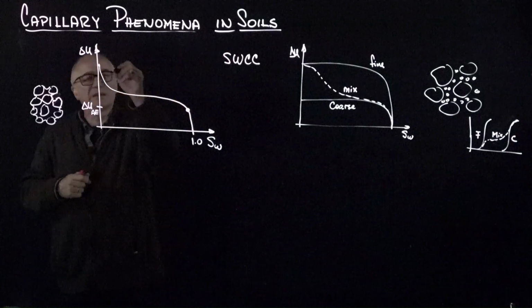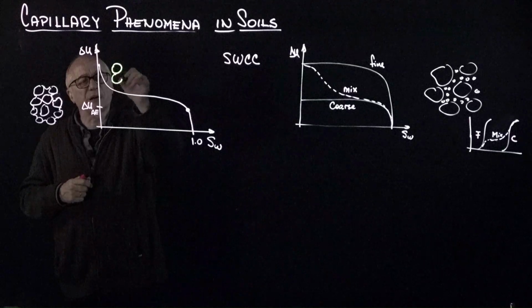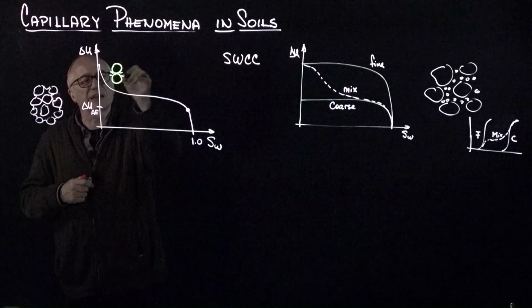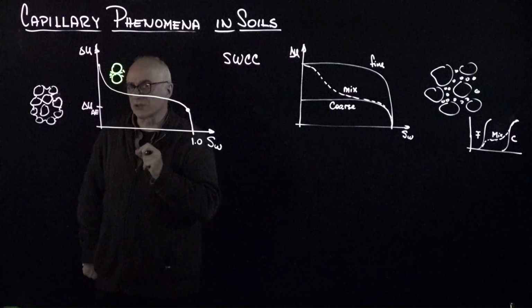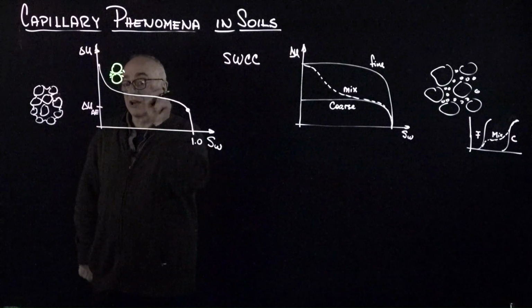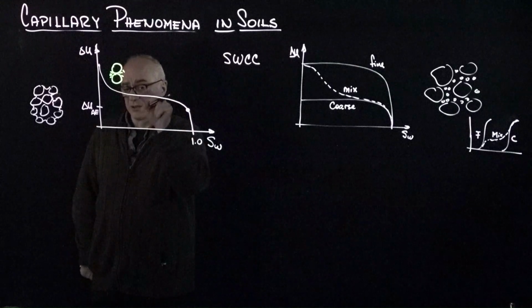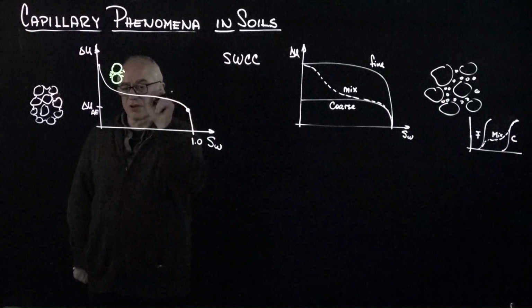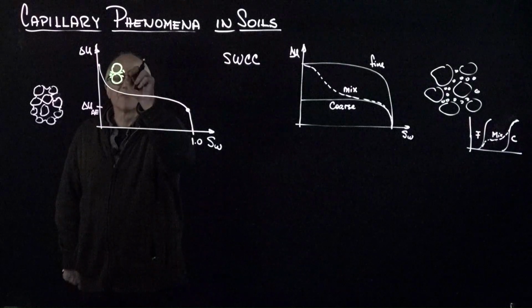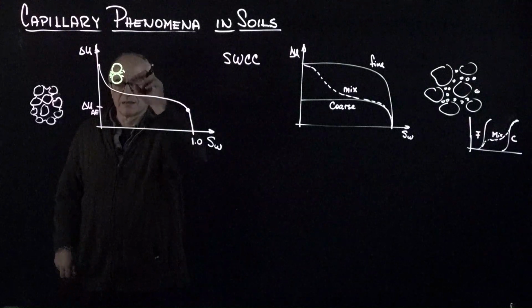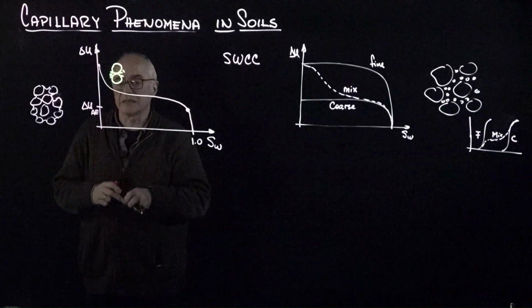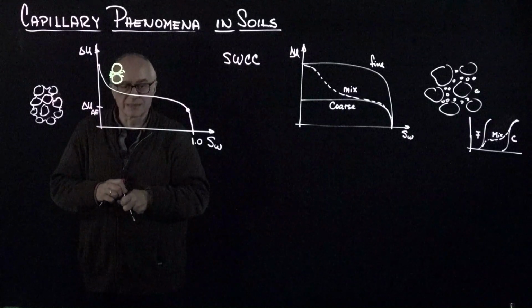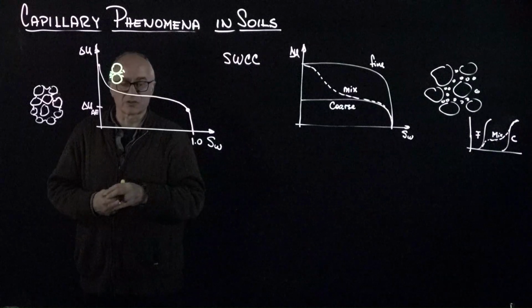And so at this point, we have fine grains coming and accumulating near the contacts of the coarse grains, and this is what the loess is. You can see some SEM images of loess, and you see these fine-grained abutments that accumulate near the coarse grains, helping the stability of loess under high suction conditions.